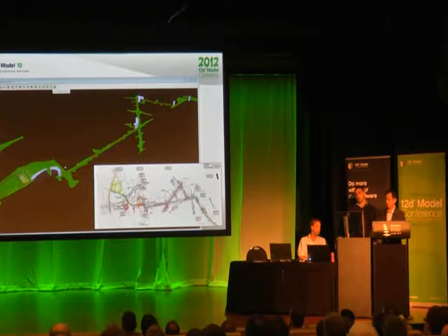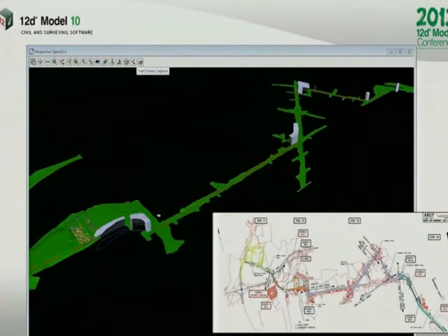The green color bit is actually the survey model that we created. And we also have to create any obstacle, which is shown in the gray color. It's any building boundaries, obstacle, fencing, bridge piers, retaining structure, anything, even heavy vegetation. So we have to build everything into a super tin very carefully and accurately in order to get a better result at the end of the day for the sight stopping distance check. If people have a sharp eye, you can also see on the left-hand side, there's the depot there.